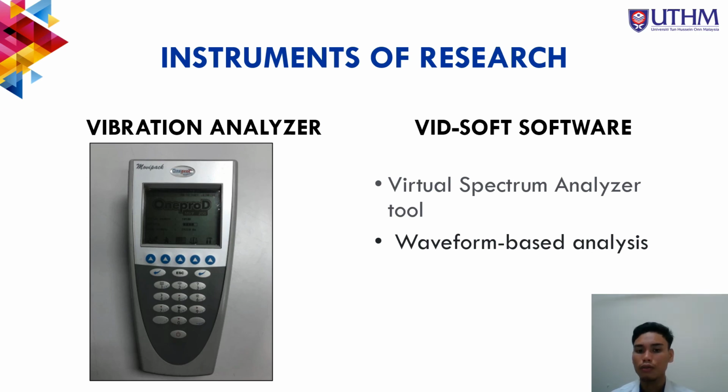The VIDSoft software is a virtual spectrum analyzer tool, which is waveform-based analysis. This software will convert it into the vibration spectrum in three directions, which are the vertical, horizontal, and axial directions. These directions are vital to locate and detect the fault in the pump.